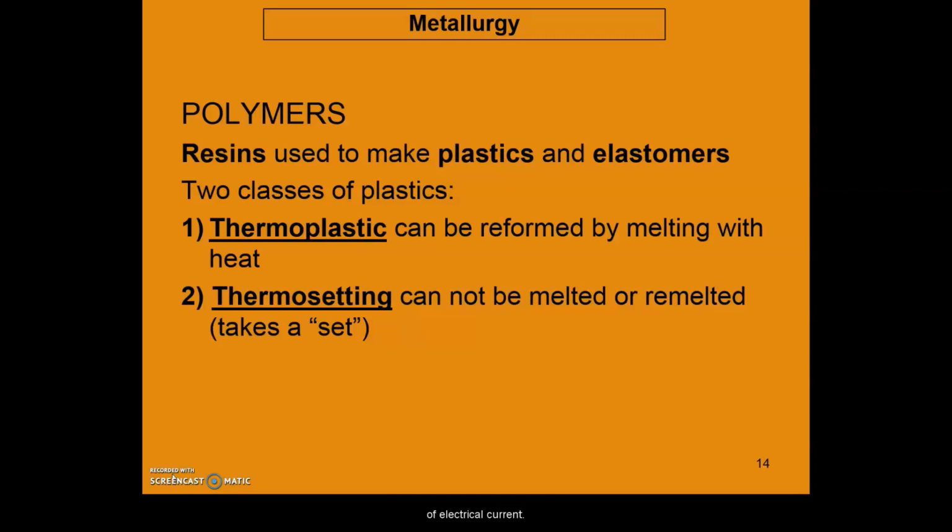They resist atmospheric and other forms of corrosion, offer good compatibility with human tissue, or exhibit excellent resistance to the conduction of electrical current. The polymer plastics can be divided into two classes, thermoplastics and thermosetting plastics, depending on how they are structurally and chemically bonded. Thermoplastic polymers comprise the four most important commodity materials: polyethylene, polypropylene, polystyrene, and polyvinyl chloride.